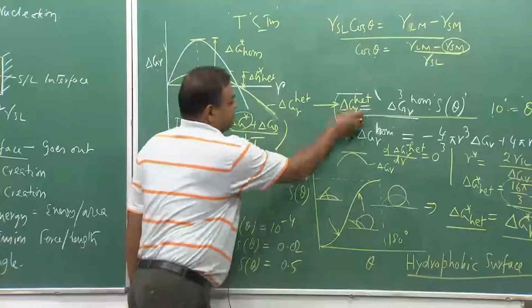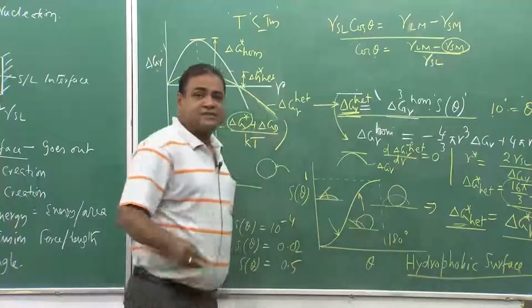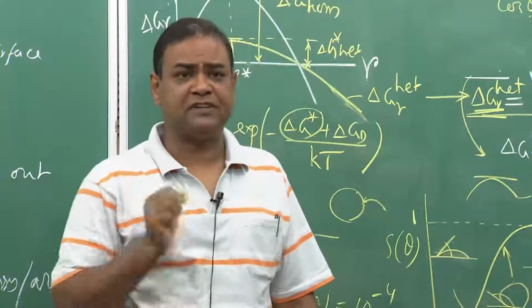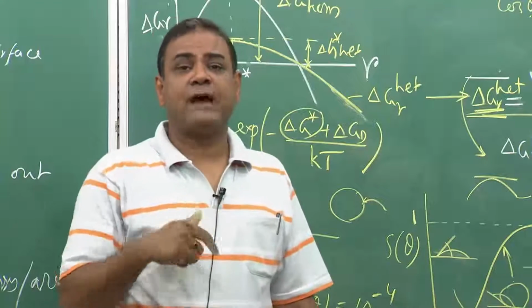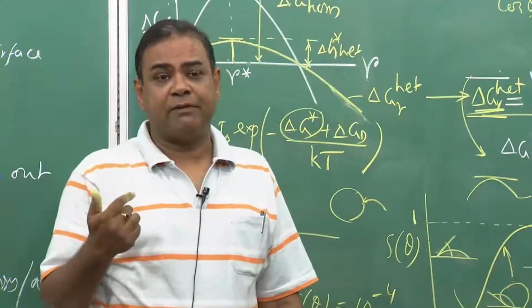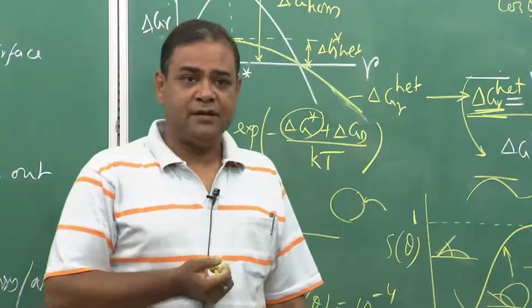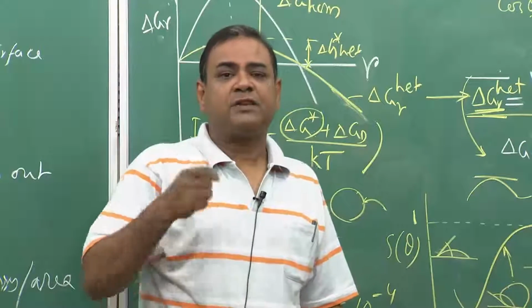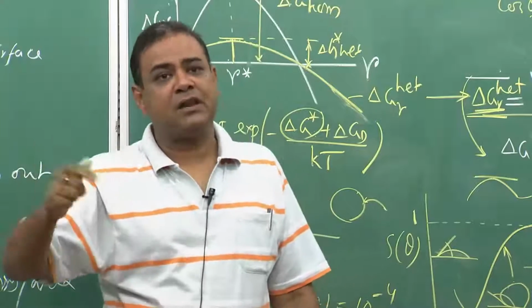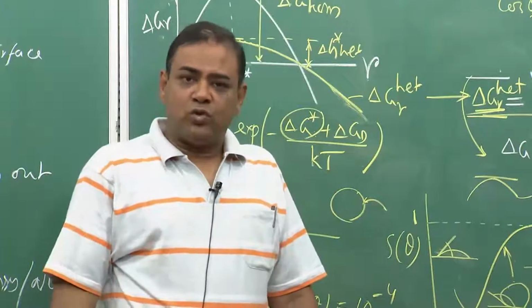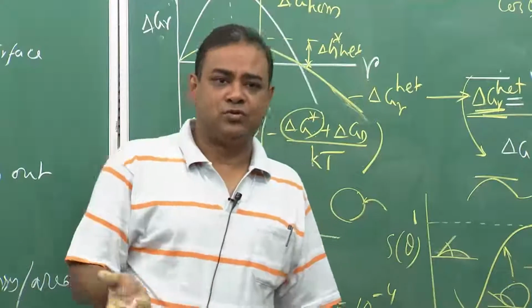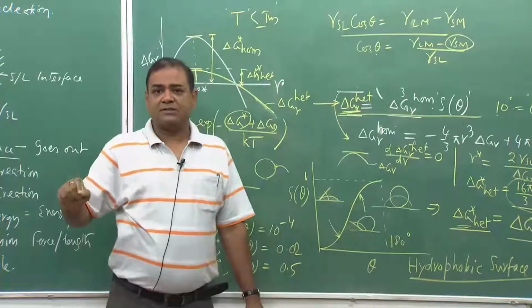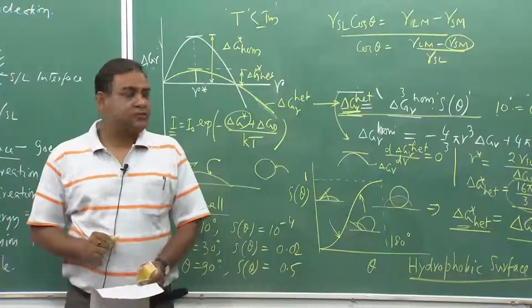Okay. So, this inoculation is decided by the wettability of that inoculant, and finally, it has to reduce this term or this term. Okay. So, for this inoculation, there would be many factors. One major factor is wettability, and also there are factors like low surface energy, as we have explained, and surface roughness is another factor. Then there is compositional variation: sometimes we add inoculants which have to react with the metal and form a chemical bond. That information would be very critical, but we will not get into it. But at least from these expressions, it is very clear that we do add inoculants to make very, very fine structures. Okay. So, let us stop here.